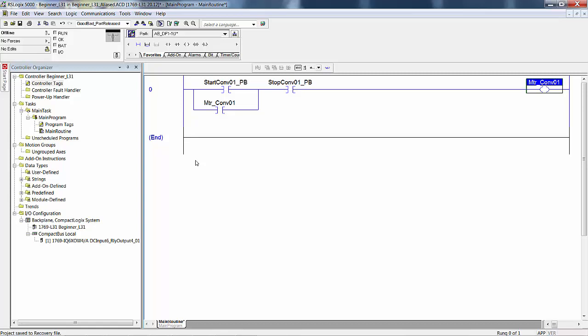It is not hard to justify using a separate controller with distributed I/O in each of these 7 distribution areas in this big distribution center. The cost for an additional processor and power supply pales in comparison to the money saved in design time, maintenance, troubleshooting and downtime if you have a separate controller and all 7 controllers start out with 100% identical programs. Or you can put it in one big controller and then just have multiple programs. So you have that option.